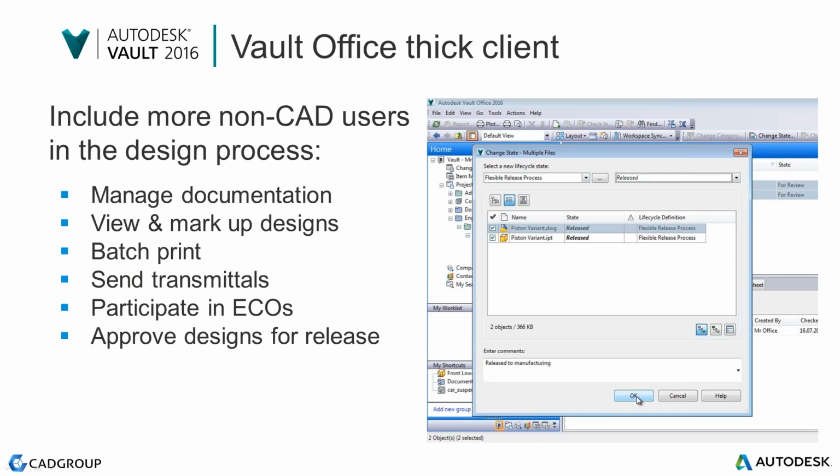We've got the Vault Office Thick client. Now the Thick client was there previously, but in 2016 it has been enhanced a lot so that non-CAD users can now manage their documentation, view and mark up designs. They can participate in the ECOs, they can approve the designs. The only thing they are really restricted to is modifying CAD files. They cannot check in and out CAD files with the Vault Office Thick client.